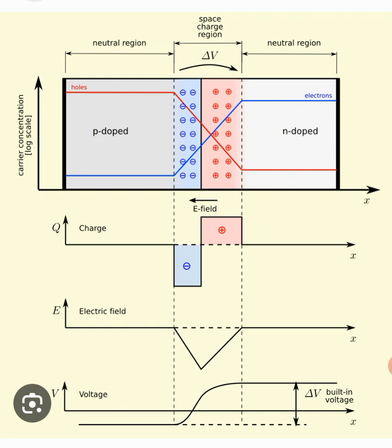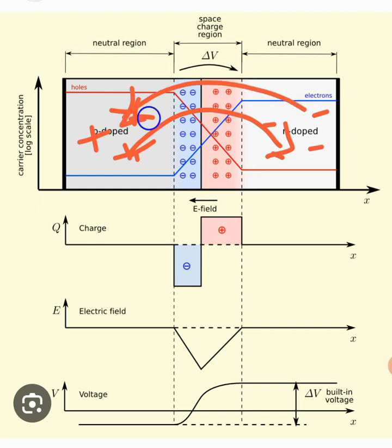So what happens when P type semiconductor material is joined to the N type semiconductor material, as shown by this line right over here? The electrons, which are the majority charge carriers in the N type, and the holes, which are the positive charge carriers and the majority charge carriers in the P type, try, because of the electrostatic force, to diffuse from one region to another region.